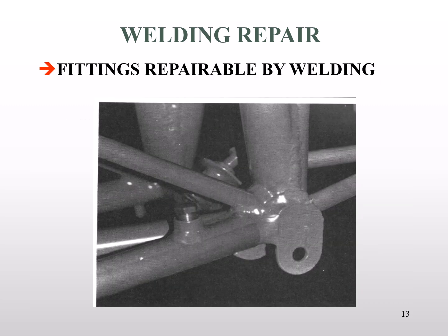Fitting. Now, what I want to point out is that a fitting in welding has a different meaning than a fitting in hardware. When I think fittings, I generally think hydraulic fittings, lines, parts and pieces, fuel, hydraulic, oil, oxygen. But in welding, a fitting is anything that's welded to create a point that we can attach another structure. So in this picture, you're seeing a welded fitting, and I'm not sure what bolts on here, but it allows attachment through hardware of another steel structure to this original steel structure.